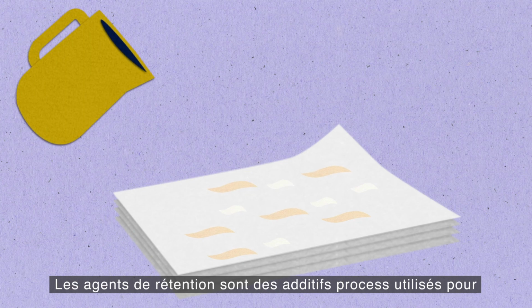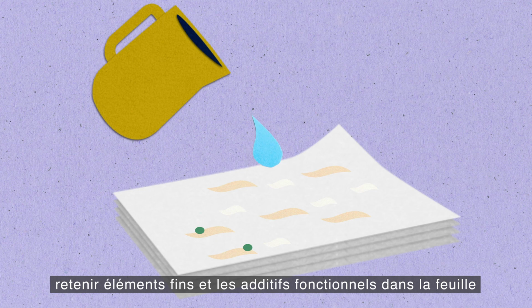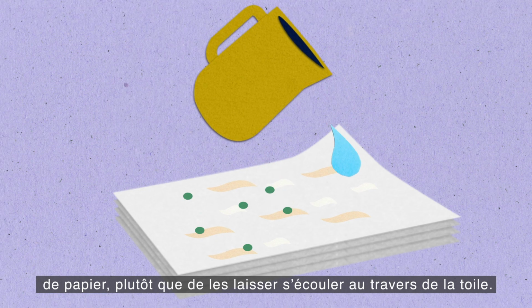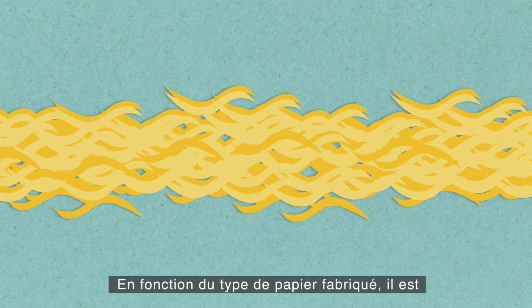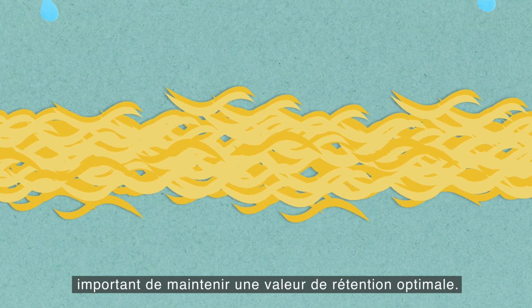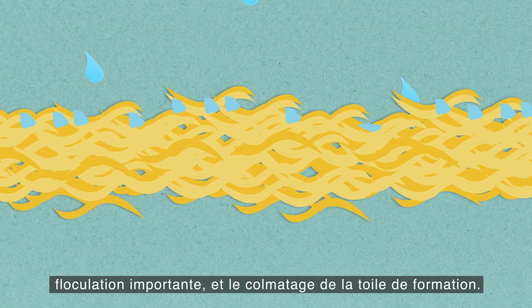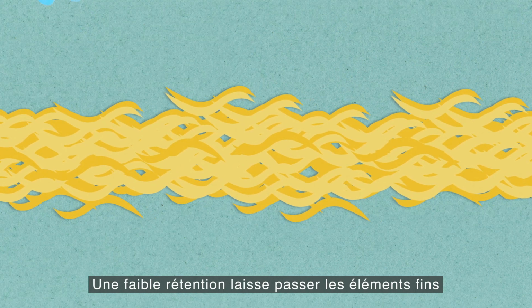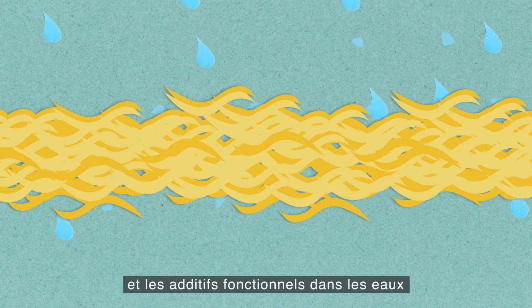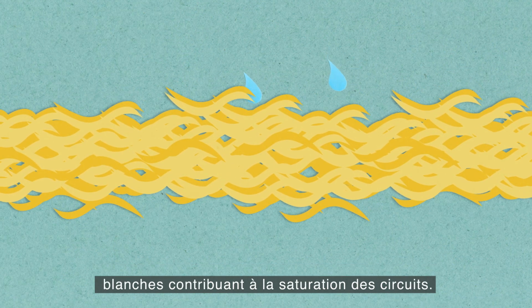Retention additives are process additives used to retain small particles and paper chemicals in the sheet, rather than draining through the wire. Depending on paper grade, it is important to have the correct level of retention. Too much retention causes high flocculation and fibers sticking to forming fabrics. Not enough retention lets small particles and chemicals drain through the sheet and accumulate in the whitewater system.